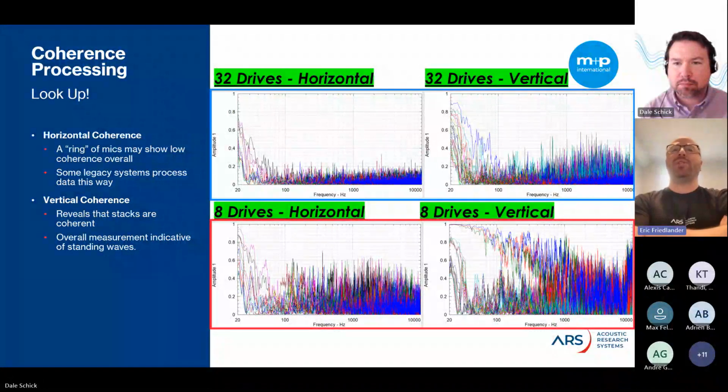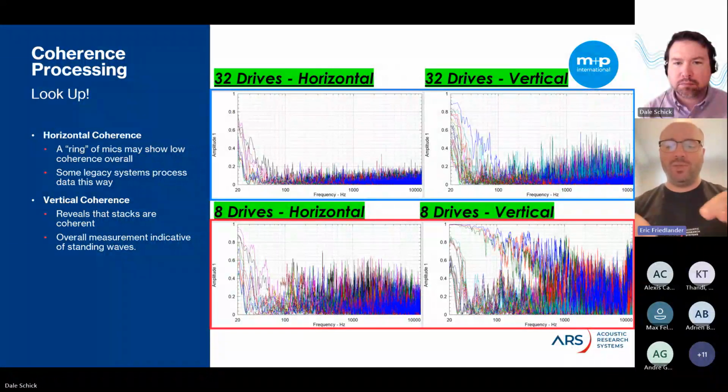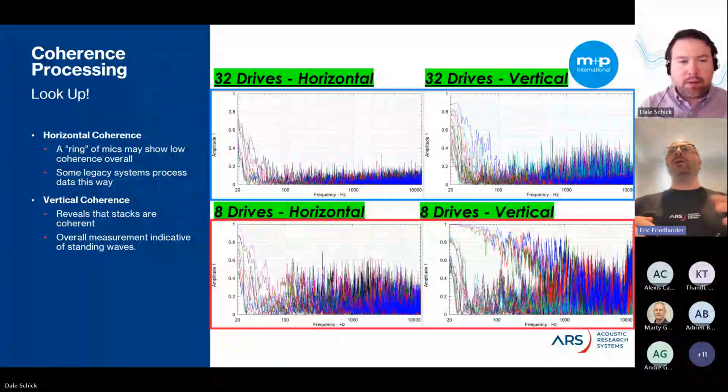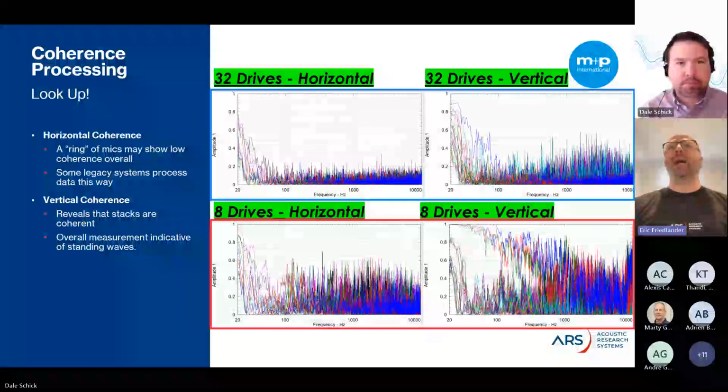If you look at NASA Handbook 7010, using an older approach, they say put a ring of microphones, and it's easy to look down from your top-down view and see that these microphones are spaced apart and these sources are probably unrelated to each other. So we're getting indications of a uniform diffuse field where the sound is highly randomized and even.